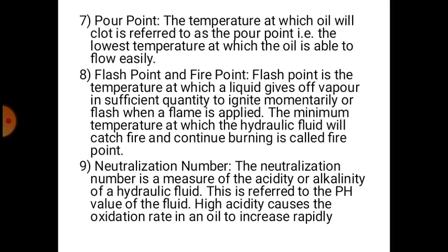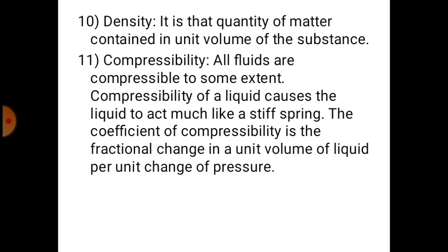Neutralization number. The neutralization number is a measure of the acidity or alkalinity of a hydraulic fluid. Density. It is the quantity of matter contained in the unit volume of the substance. Compressibility. All fluids are compressible to some extent. Compressibility of a liquid causes the liquid to act much like a stiff spring. The coefficient of compressibility is the fractional change in a unit volume of liquid per unit change of pressure.